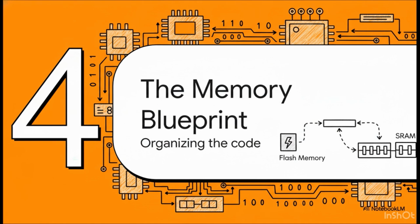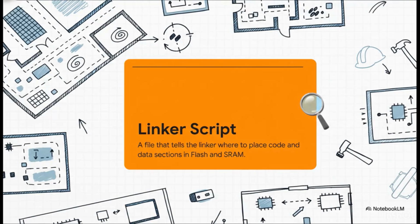For that, we need a blueprint. And this blueprint is called the linker script. This is one of the most critical and, honestly, most overlooked files in bare metal development. If our chip is that plot of land, the linker script is the detailed architectural plan that tells our builder, the linker, exactly where every single function, every variable, every little piece of code is supposed to go.